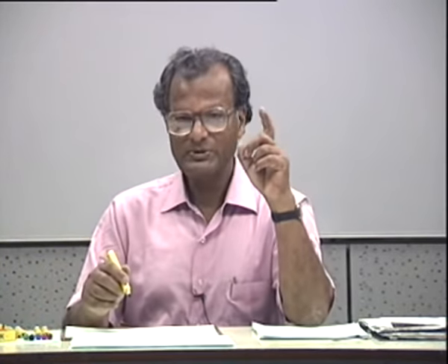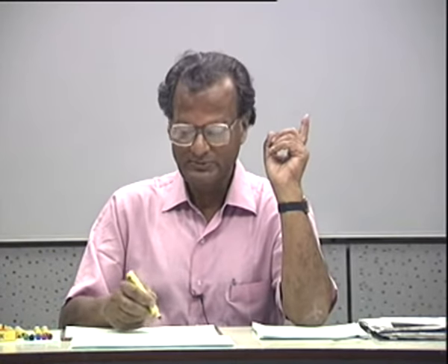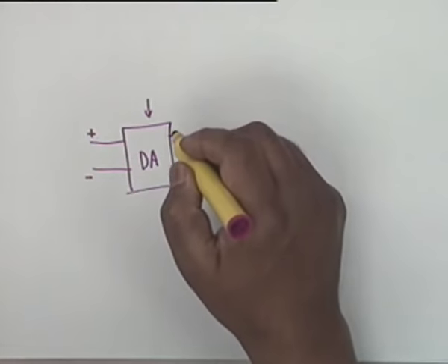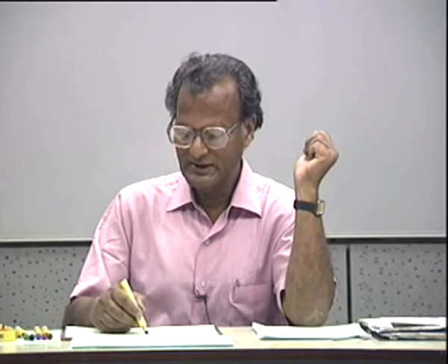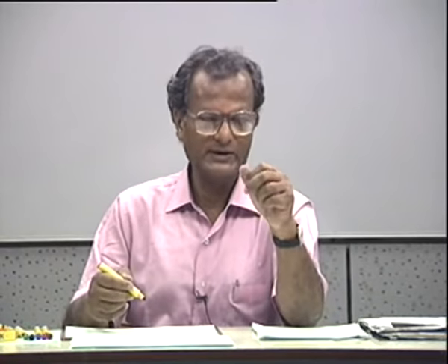But what is the property of a differential amplifier? What about the output impedance? Input impedance can be made high if you use those two Rs. Output impedance is usually large, and therefore it's a voltage to current converter. In other words, these are transconductance amplifiers. Is that correct? There is a high input impedance, and therefore what one does is, after one or two of these differential amplifiers,